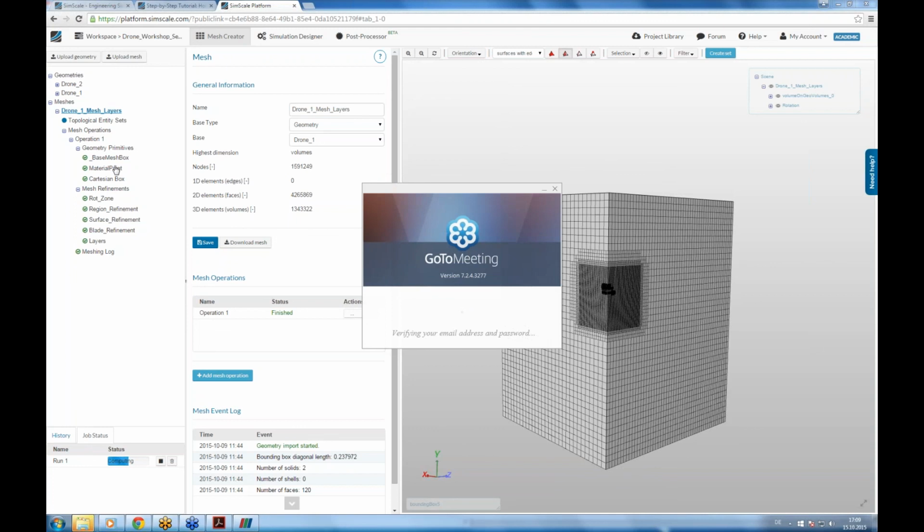The meshing tool does not know where the area between them is, so you have to specify it. Because there are two possibilities: because this box is a kind of volume, you could also mesh inside of the geometry. With the material point, you define in the end where the outside of the geometry is, and where the material point is, there the mesh will be created. Did that answer your question, Prabhu?